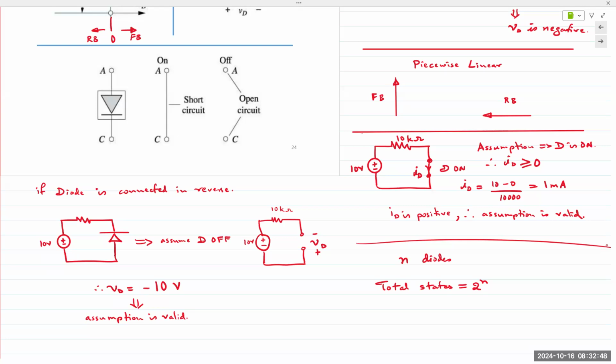Yes. So you said that you get an increase in voltage if the diodes are in series? Yeah. If you think about it, if you have one diode and you're forward biasing the diode, you would need 0.6 volts to turn it on. If you have two diodes in series, now you need 1.2 volts to turn it on. Three diodes in series, you need 1.8 volts to turn it on.